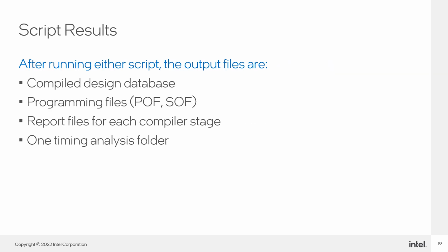After running the scripts or commands in the previous slides, you end up with a completely compiled design along with POF and SOF programming files, report files for each stage of the compile process, and the timing analysis report files.